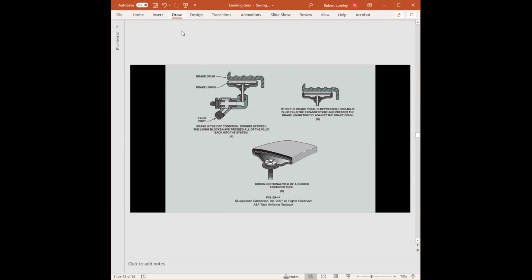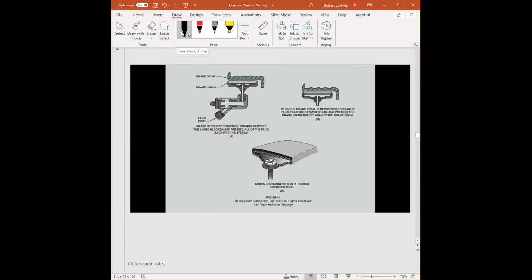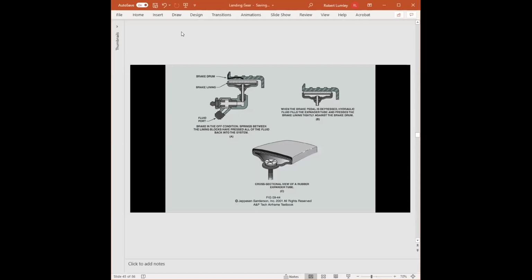Probably. All right. So from the mechanical brakes, with the Johnson bar and cables and such directly putting pressure onto the wheels, they went to what's called a drum brake. I know a lot of people are unfamiliar with drum brakes, but the drum brake used in aviation was kind of special. It's known as an expander tube. What they're showing here is the drum, and the drum would actually come down like so, inside the wheel.